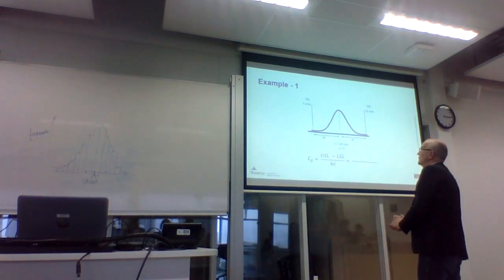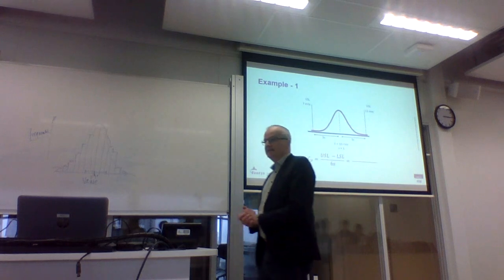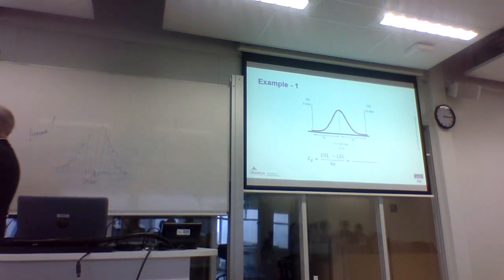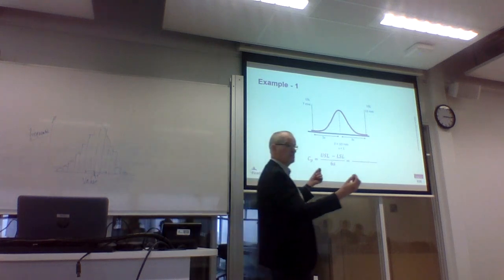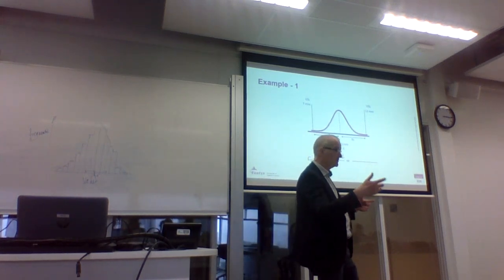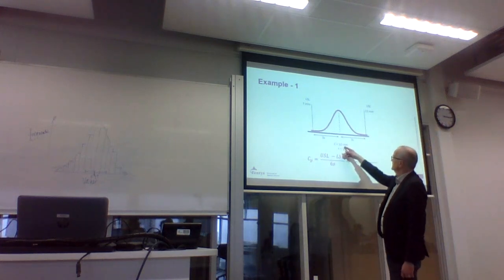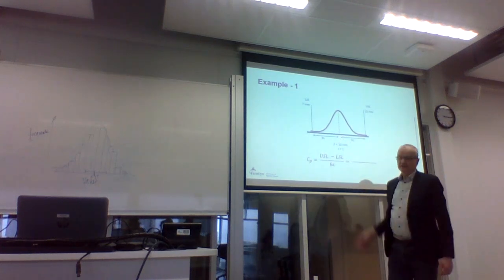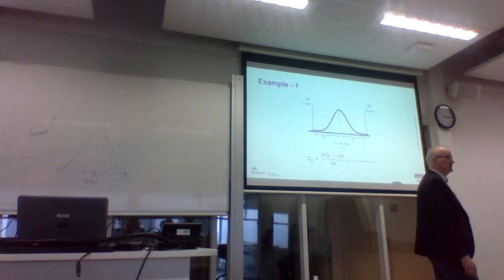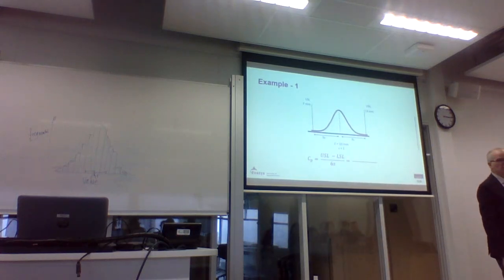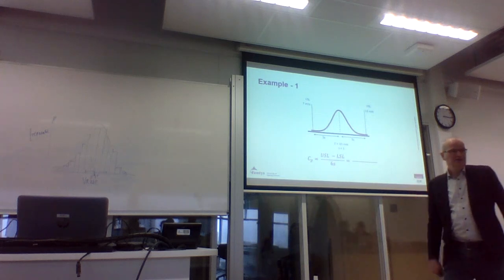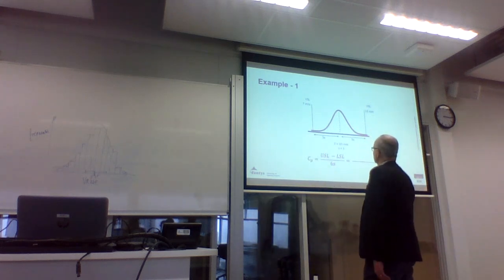What you see over here is a normal distribution. It's a bell-shaped curve. I measured the average of this process. It's a diameter, let's say the diameter of a hole: 10 millimeters. That's the average. If I drill a hole, the average diameter would be 10 millimeters. It's a bad process, by the way, because there is a large difference in there, but anyway, it's just for example.